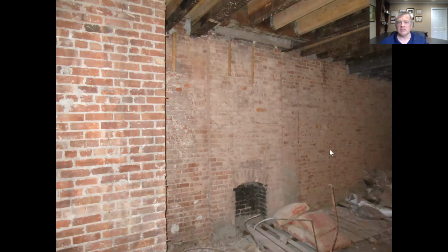Remember that fireplace? I'm not a big fan of fireplaces structurally. You know why? Because if you go straight up from a fireplace, which is where the smoke wants to go, it's hollow, which means structurally, we're going to have to build around it above to make sure our joists above are picked up properly. When I see fireplace, I think voids. And that's what you have in the wall. It's a void. Obviously, it's a void. It's where the smoke had to go up.